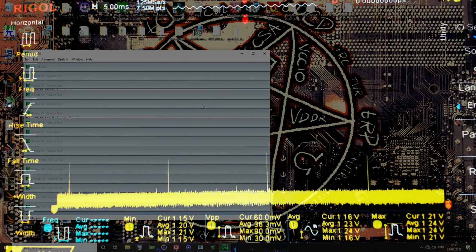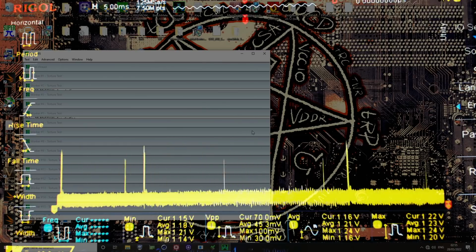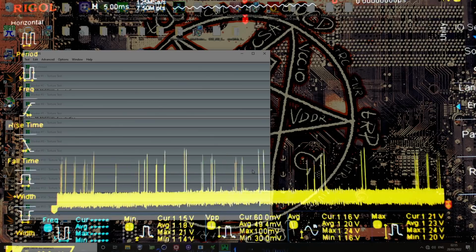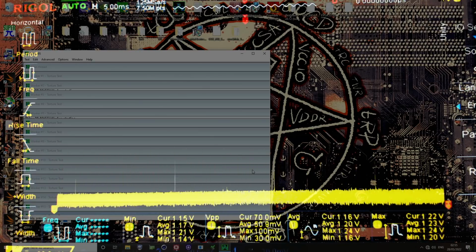Oh, boy. Oh, man, that is a huge difference. That's insane. Oh, why? Well, that explains why I felt like I was testing the Unify-X with VCC sense the whole time, and I was sitting there going, these LLC settings don't really make a lot of sense, because the step sizes between them are really, really small. Right, like mode 1 to mode 2 is a V-droop difference of 15 millivolts, which is like, what? How? Why would you even have settings that make a 15 millivolt difference?